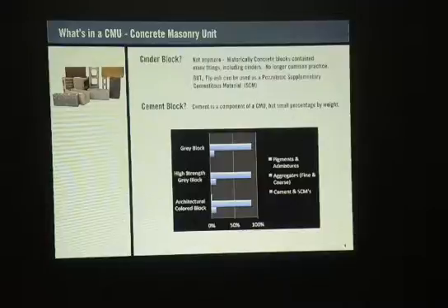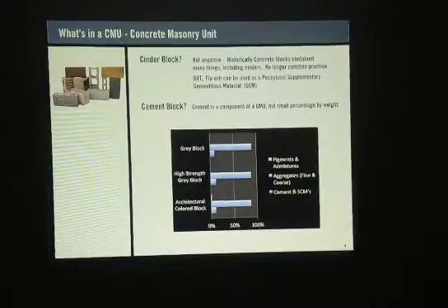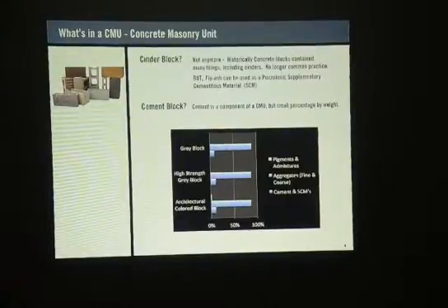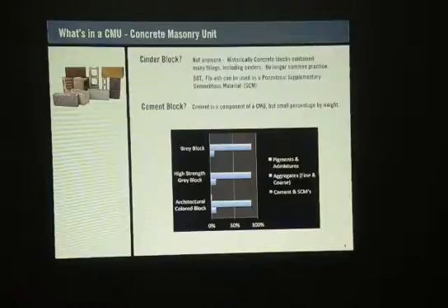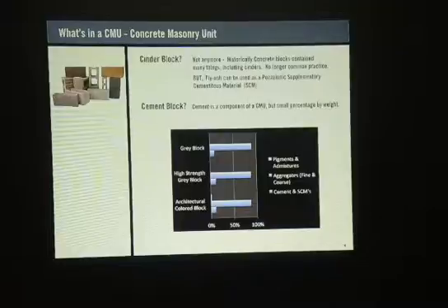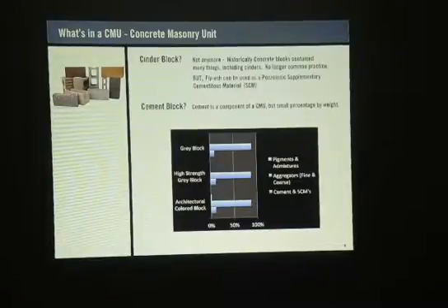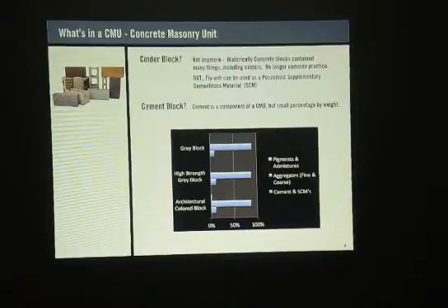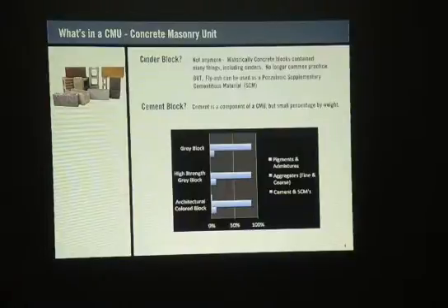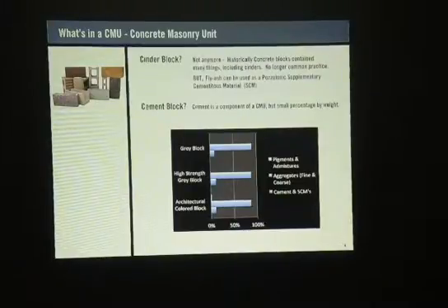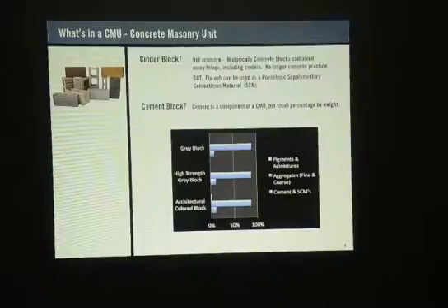If we were looking for high strength, we're going to get a range of about 1 or 2% more. So somewhere in the 10 to 12% range, we're going to have a high strength block, okay, which has a higher compressive strength, whereas normal block will be lighter and not as high. As far as the ASTM C90, the high strength does have higher requirements. It's almost double, as a matter of fact. So that's important too.